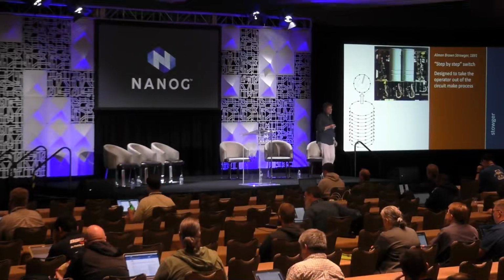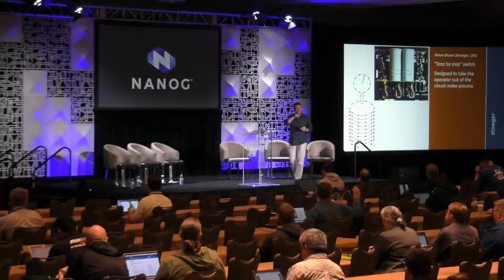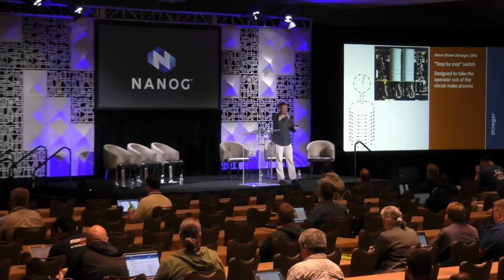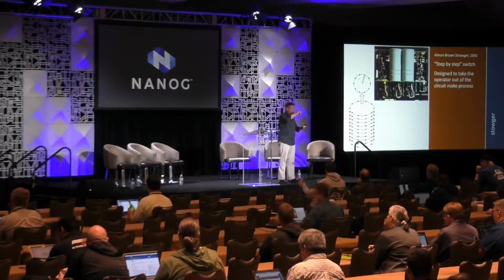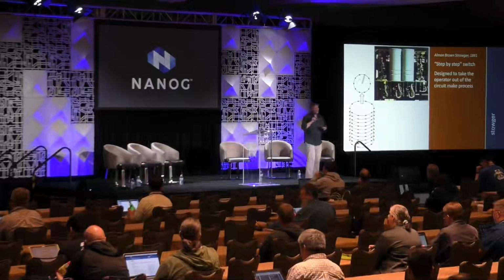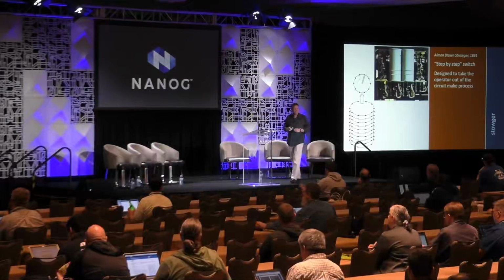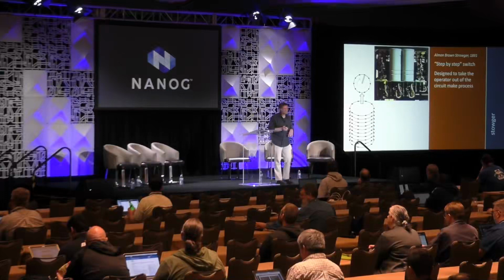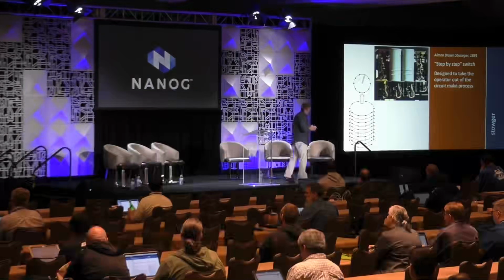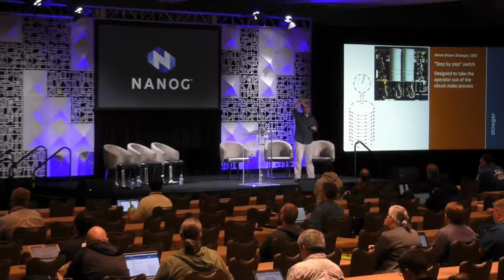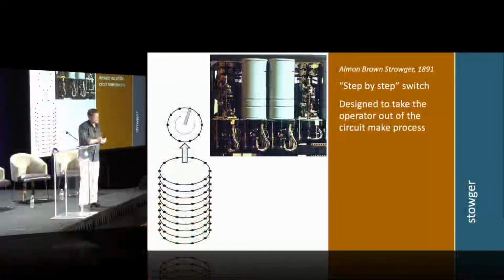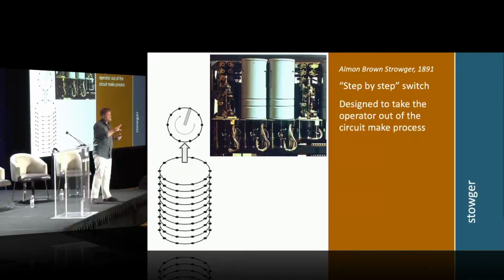And the way this works is that, you remember the old dial-type telephone where you have the circular thing, and it's not even like a pad, so that is actually driving a stepper motor. And there's actually 2 stepper motors in a Strowger switch. When you dial the first digit, it drives the armature down the wafers, and you can kind of see the wafers here. They're circular wafers. The second digit you dial drives the armature around the wafers using a stepper motor, so that you can cover 2 digits in each one of these.